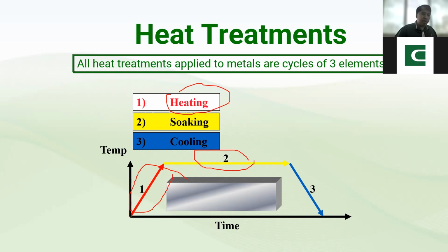Ordinary carbon steel in accordance sa ASME Section 8, the soaking temperature is 593 up to 649. So, mahirap namang makita sa time temperature graph yung 649, no? At saka 593. Ilagay mo na lang sa 600. Igitna mo na lang. So, tapos, depende yan sa kapal. For every 1 inch, 1 hour ang soaking. So, yun yung second part of heat treatment.